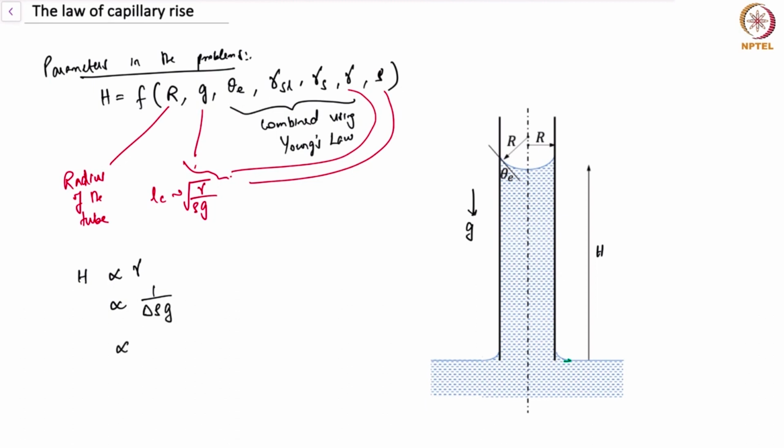The smaller the tube, the greater it would rise, because a thinner tube means surface tension basically becomes more important, and that's again what I was saying in terms of the radius versus the capillary length. A smaller tube would mean the fluid could rise higher because surface tension would dominate over gravitational forces, and therefore again we would have an inverse proportionality.